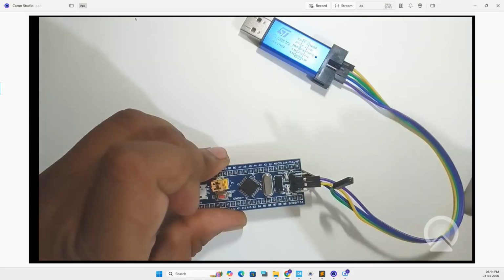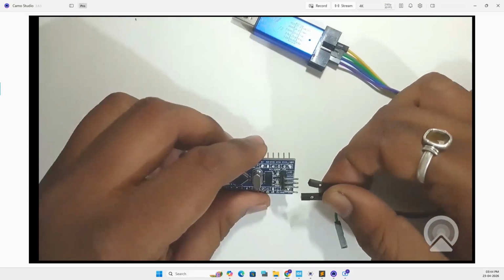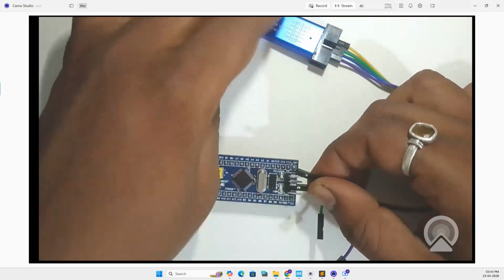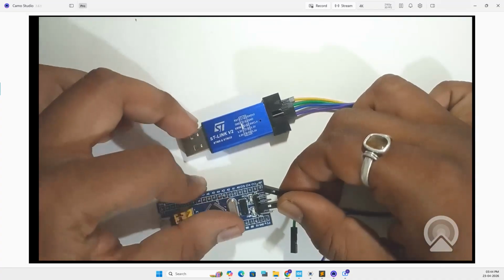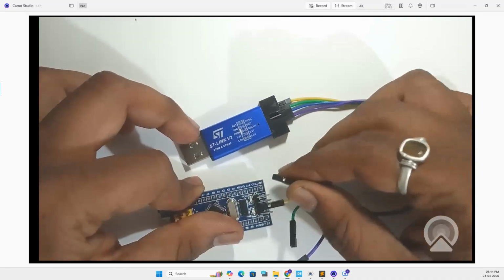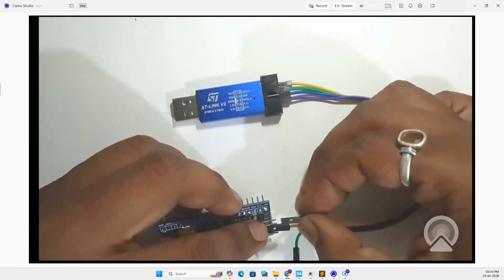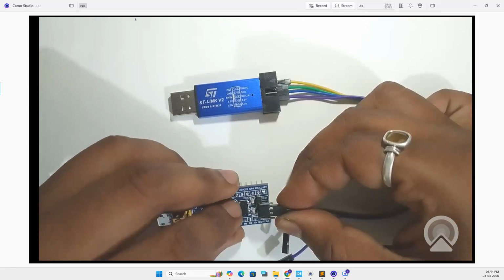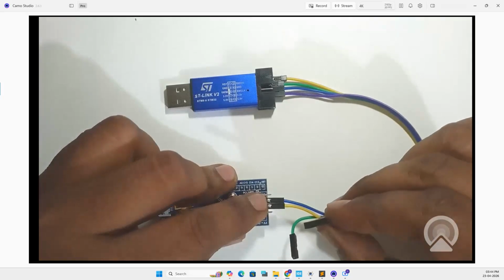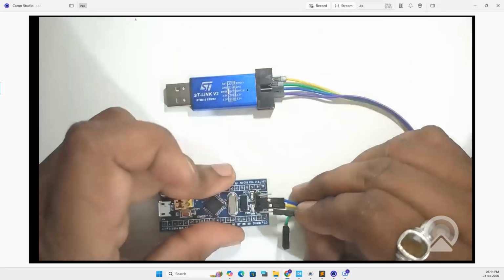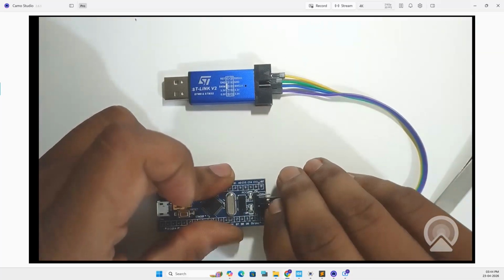Yes. So blue wire. Sorry, this one is purple. This one is blue. So yellow is SWDIO. Okay. After that blue wire that is SWCLK. So here also we are having this. You can see this after tilting, SWCLK is there. Okay. After that this purple wire is power supply, that is 3.3. So we are going to connect it over here. This is my 3.3.